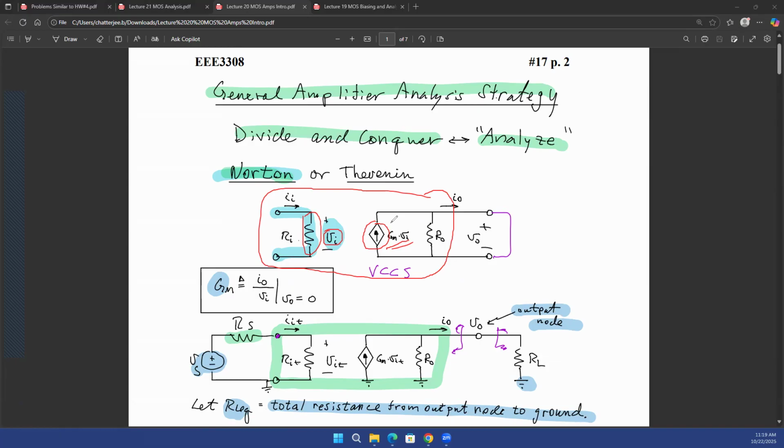We are starting from the point where we left off when we were discussing op-amps, right? But as you see, the AC equivalent model looks very similar. The only difference is that you had an input resistance Ri, because op-amps could be non-ideal, and that non-ideality was implemented in the form of an input resistance Ri.